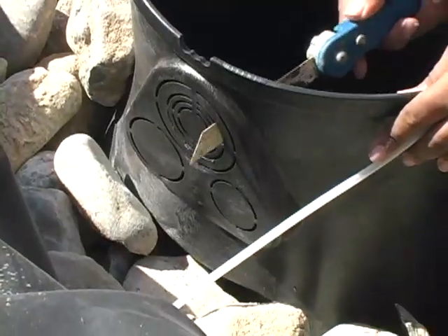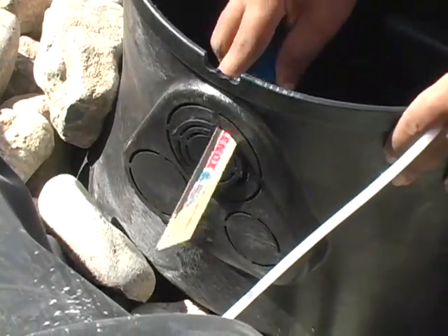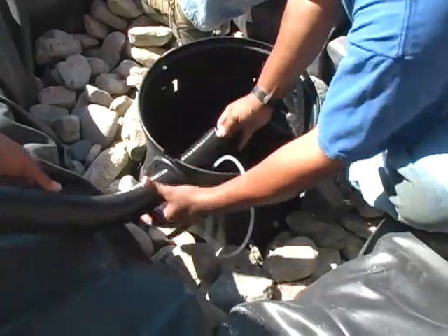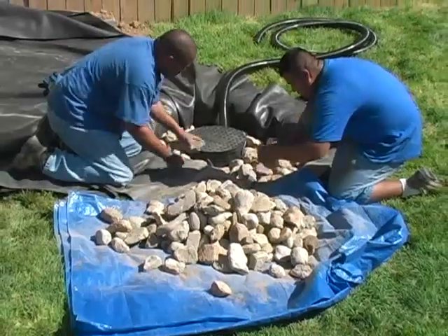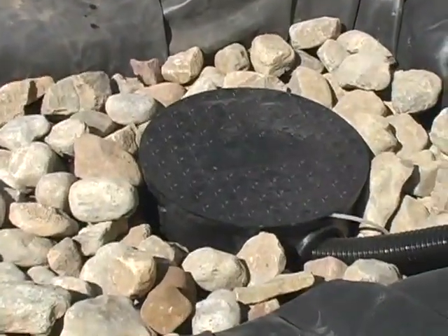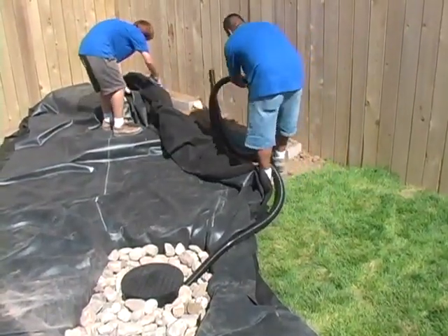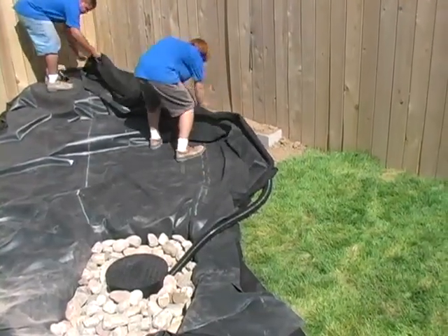Cut out one of the 2-inch knockouts from one side of the well with a keyhole saw. Slide the kink-free hose through the outside hole in the side of the well. Then finish filling the basin with cobble until only the waterfall well lid is exposed. Walk the other end of the hose up to the top of the waterfall. Conceal the hose beneath underlayment and the liner.